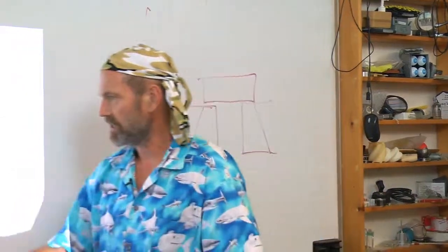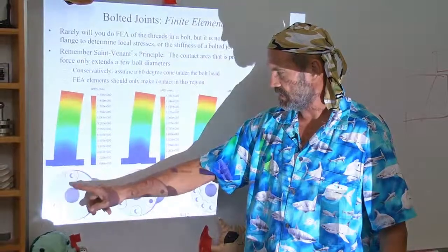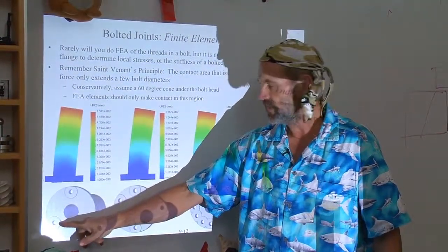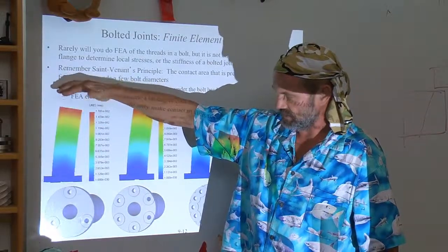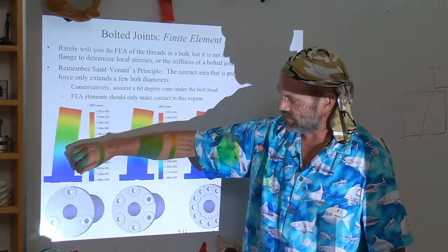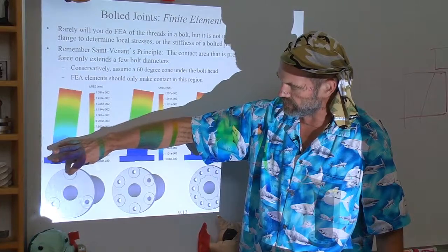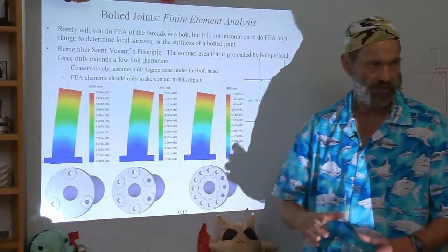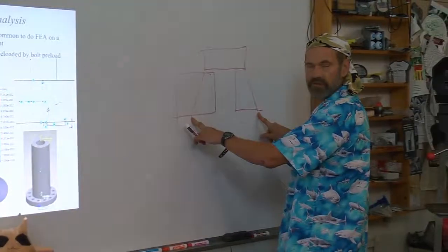And that's what's represented here, where I've made these little islands or mesas, because when you've only got 3 bolts and this column with this flange is bolted to the base, and the bolts are tightened, those stress cones expand out and really only have good intimate contact at 3 points, at those 3 areas. That area is based on this stress cone diameter.